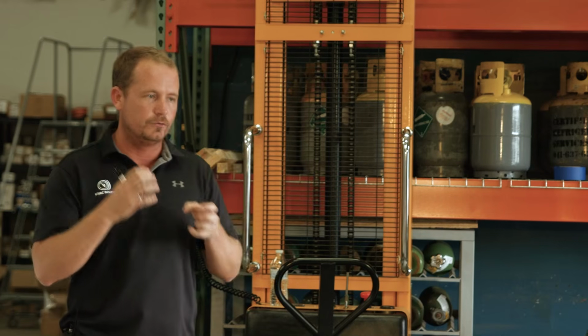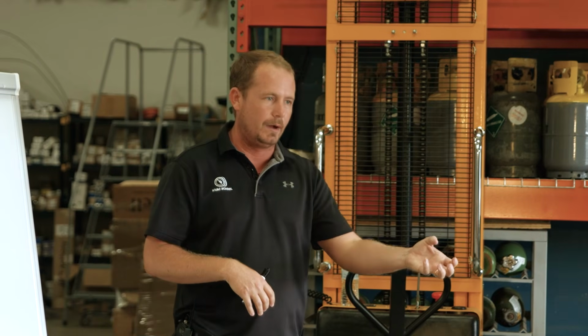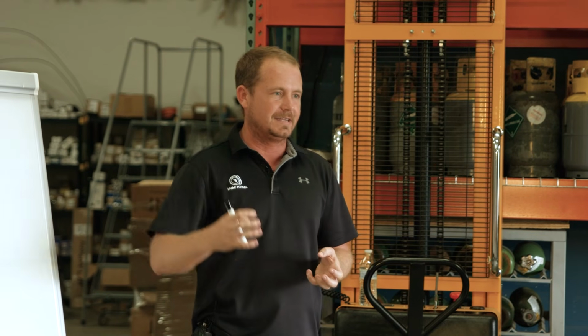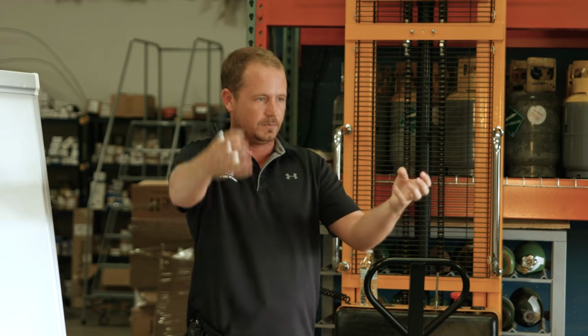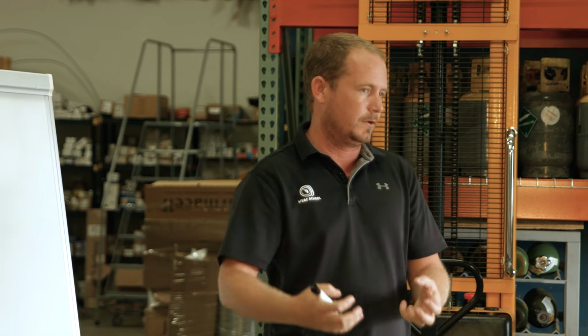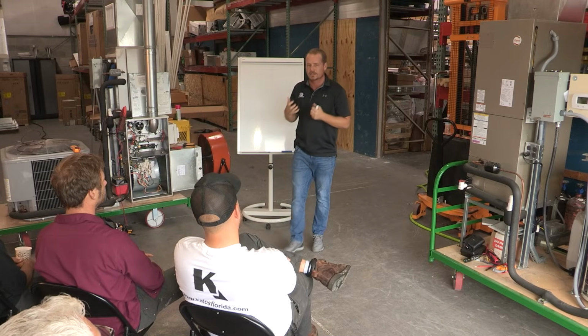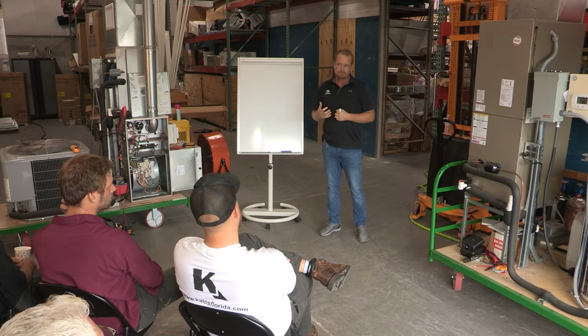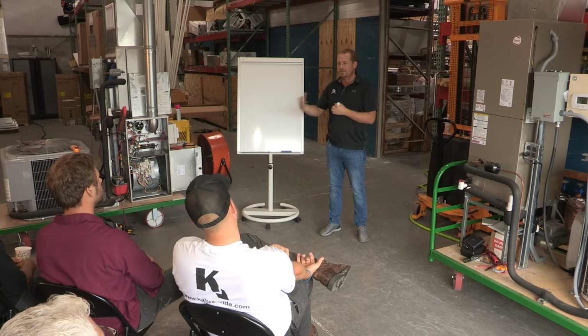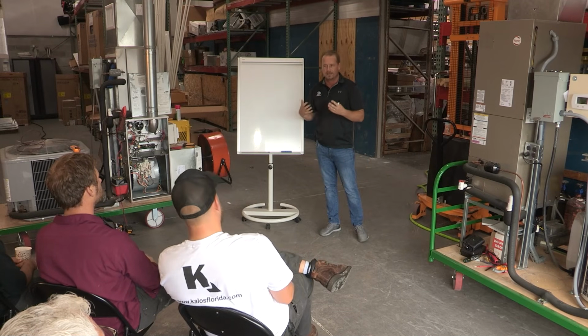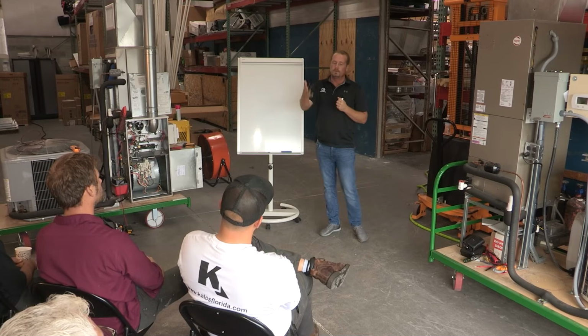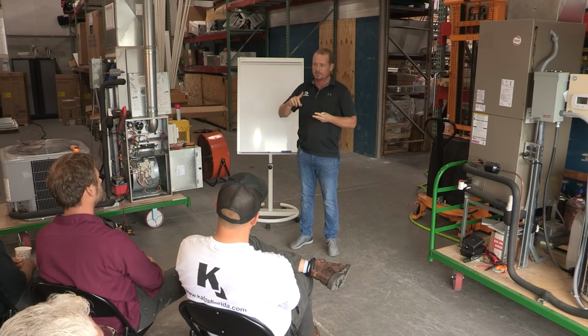So a lot of people, if you don't know that, would think, well, you'd have Y1, that's stage 1, and then you go to Y2, that's stage 2, right? But it's actually Y1 plus Y2 equals your high stage, your full capacity operation. So it's things like that. You've got to start with knowing that about your equipment. What are each of these terminal designations for? When should they be activated? That sort of thing.